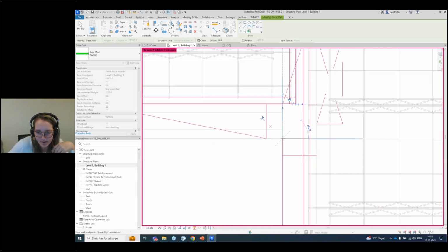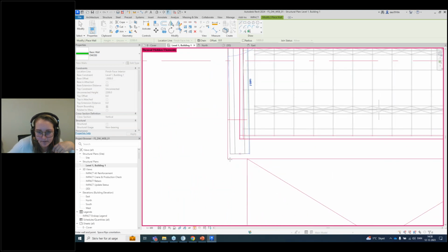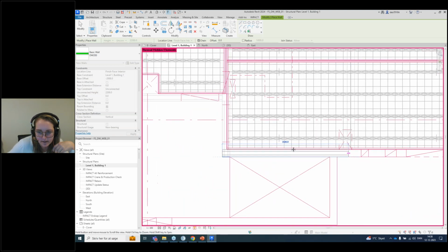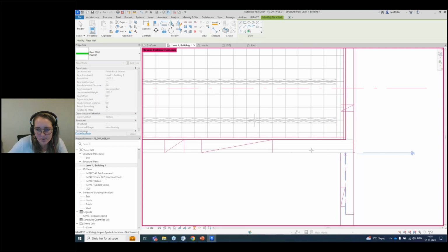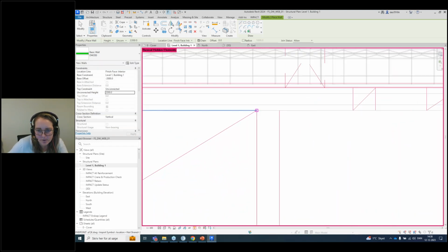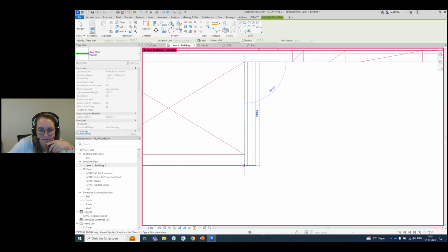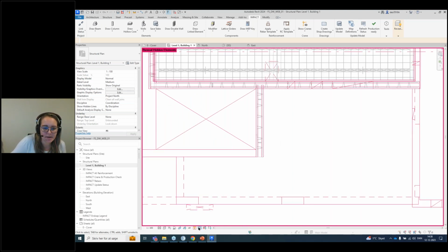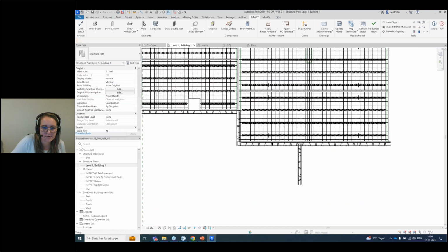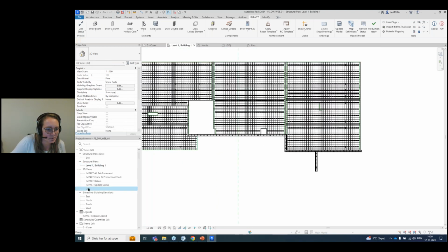So I'm going to draw it until here, and then I'm going to go down, and I'm going to continue into here, because here I'm going to do also one wall for the T connection. So like this. Okay, so now we are drawing the double walls, and before we continue, we're going to see how it looks in 3D. See if we have hit the parameters right. I'm going to switch off the underlay, and I'm going to go into the 3D.